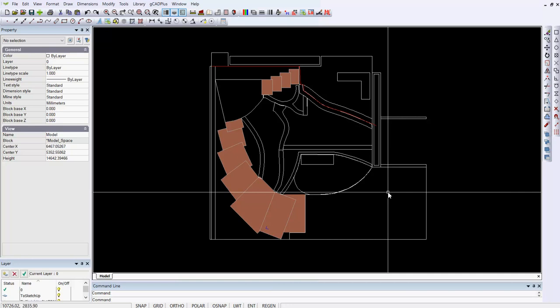So we've exported by using the copy to clipboard, put the data into a new drawing, and then exported from the new drawing in the form of a DXF file. You could skip that intermediate step of copying to the clipboard if you wanted to, but I find it cleaner and easier to work in this way. Now it's time to start up SketchUp and see what we've brought across.